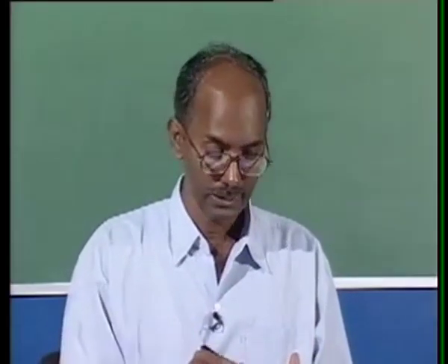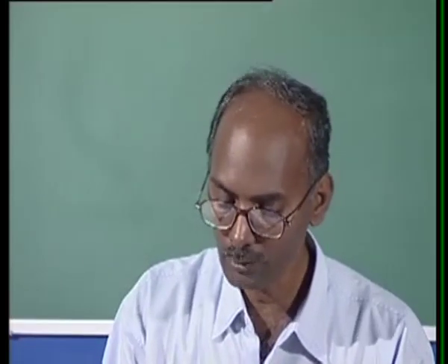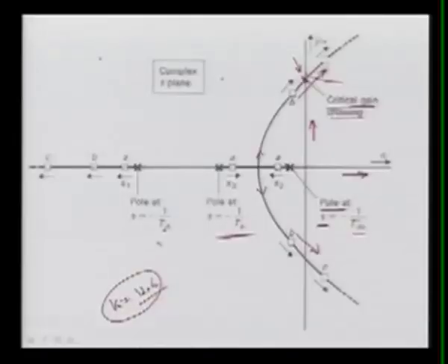And we find that the gain was very less, 12.6, which is very less. And for this, your steady state error will be very high. So what we have to do, because for the static gain we require more gain, we have to do some compensation, and then we can improve the stability of the loop. Let us see what are the various ways to improve.